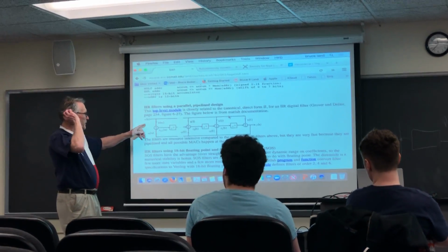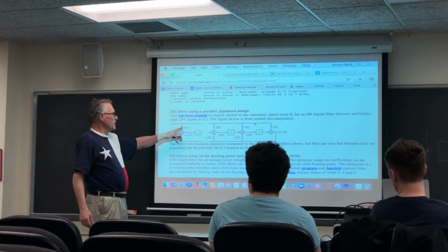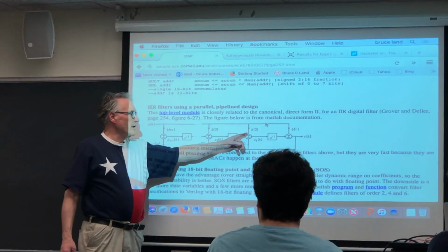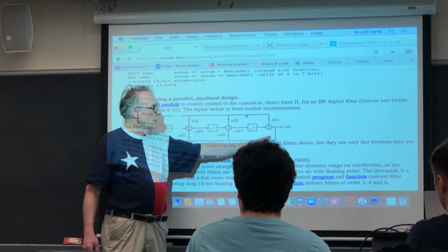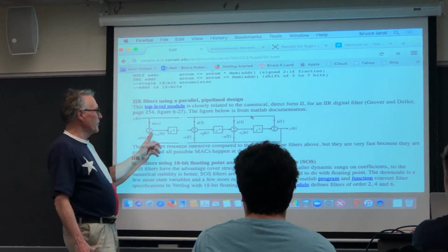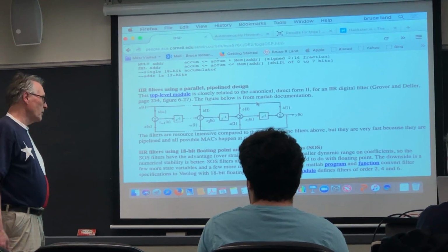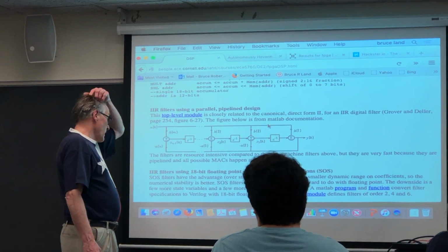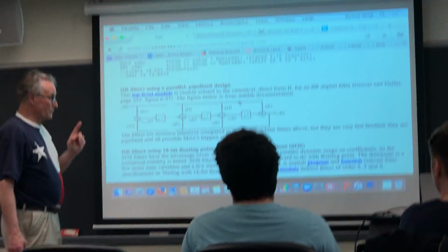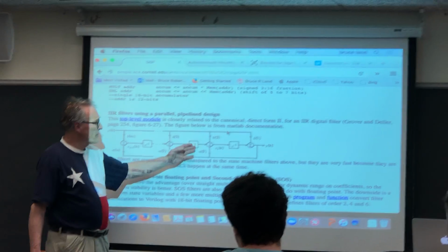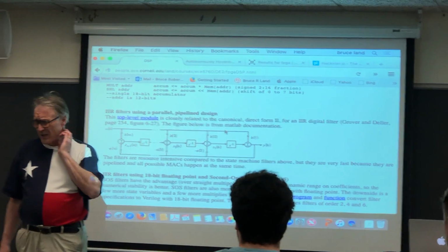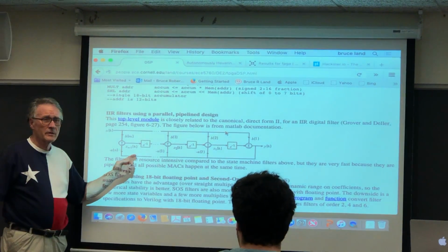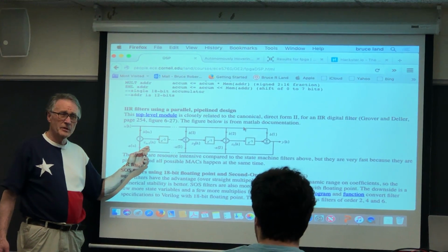An IIR filter is you have some input, you have some coefficients B, and you have some feedback from the output, which is fed back in through some coefficients A, and this particular structure minimizes the depth of the adds and maximizes the speed of this device. You can easily run one of these things at RF rate on this FPGA.